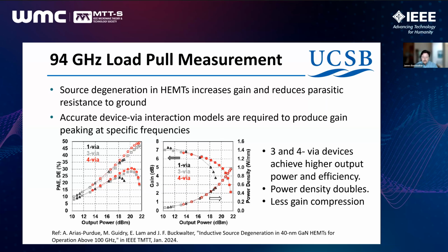And that increased output power also translates into higher PAE for the device structure. So the black, now let's move to the left plot. The black curve on the left goes from 24% PAE to something that's reaching 30% PAE.